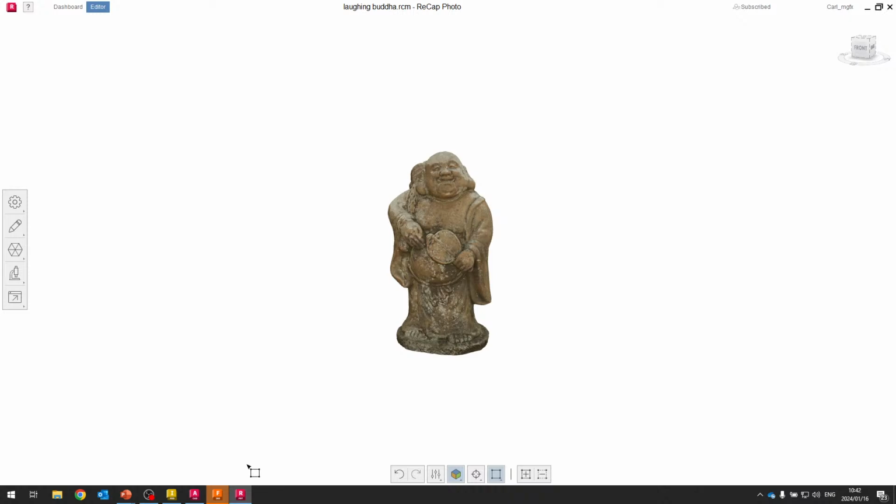A couple of work cases that I've seen this used for could be the production of stamped steel components, let's say large body panels for vehicles, maybe windshields, formed windshields or glass, to be able to scan and then quality check the process, maybe first off runs, see if there's any modification that's required in the molds or the process of the mold.